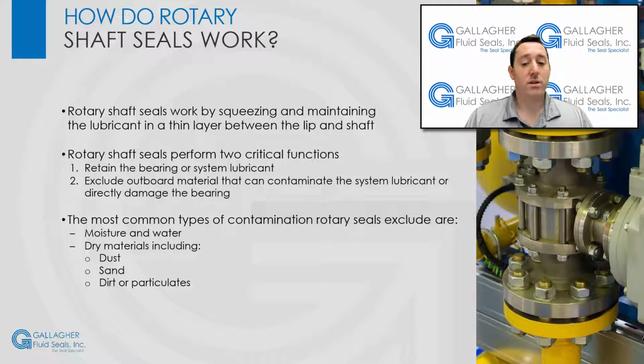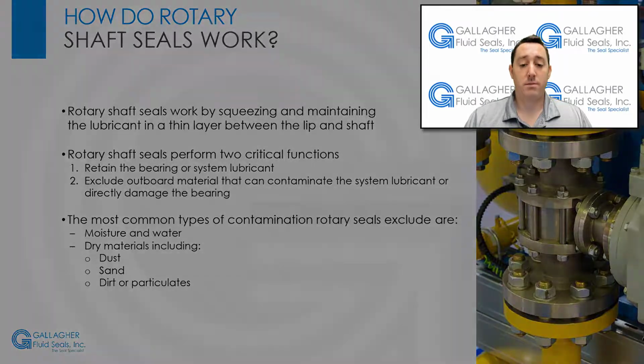Entire categories of rotary lip seals have been engineered to seal in higher pressures and faster speeds. In general, PTFE lip seals perform better in both higher pressure and speeds, but typically cost more than elastomeric lip seals or oil seals. Pressure values above 50 psi would be considered high, and surface speeds above 2,000 feet per minute would be considered high.